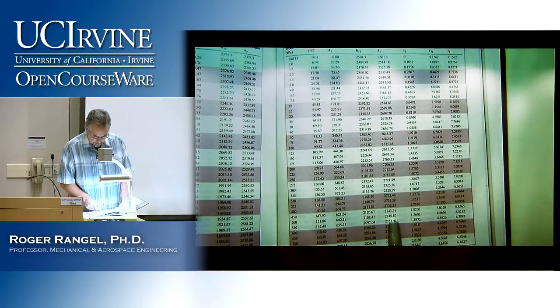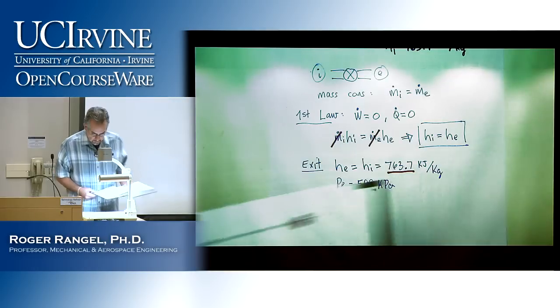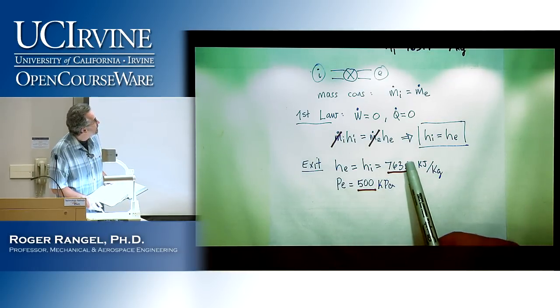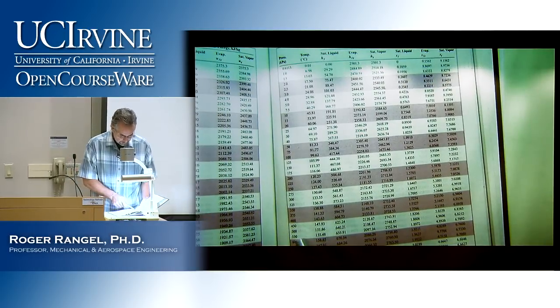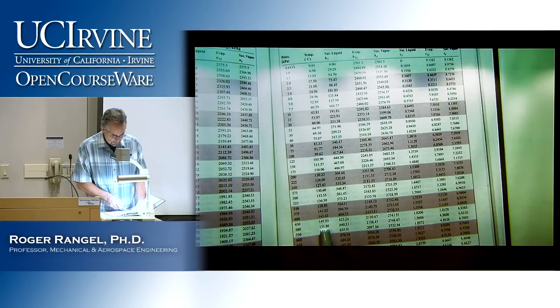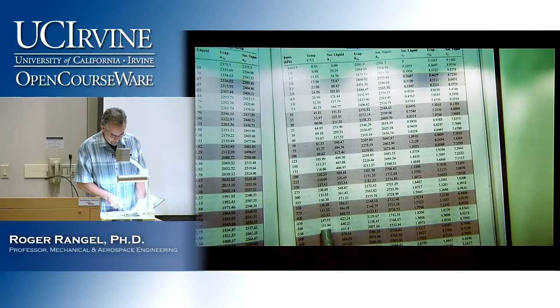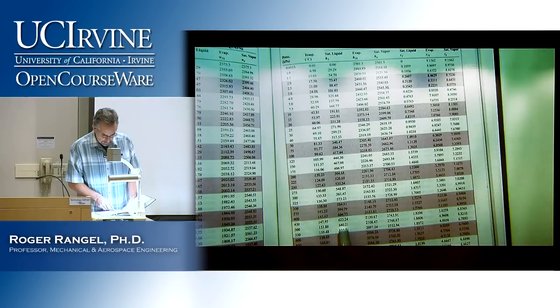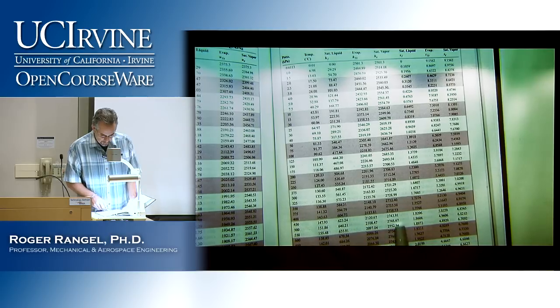to 2748. And of course it is, because our enthalpy is 763.7. But I need to take these numbers down. In fact, I will take the HF, now that I have already checked that it is in the range, larger than 640 but smaller than 2748. I will take the 640.21.